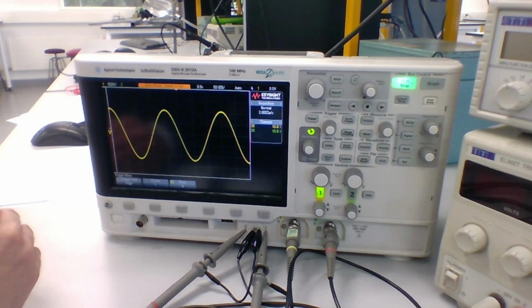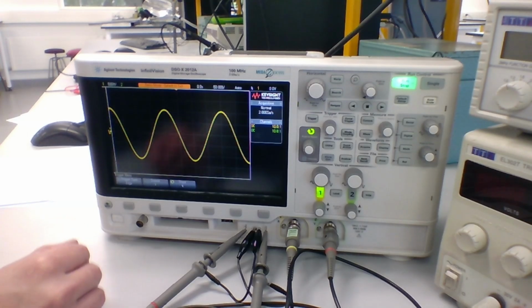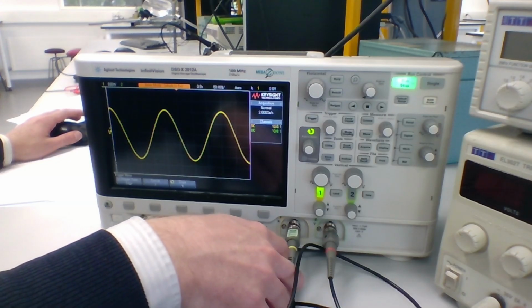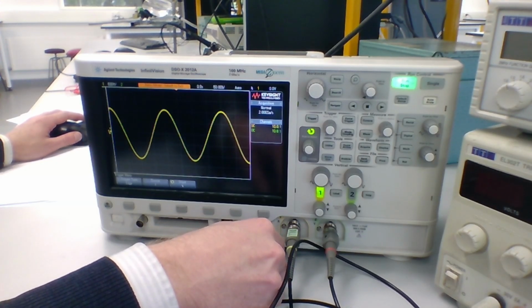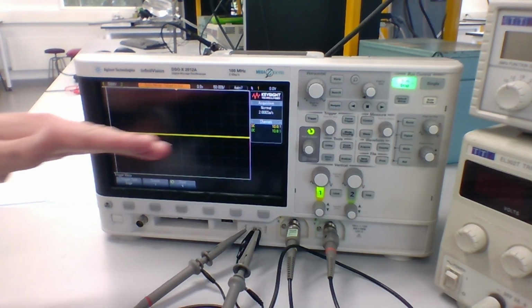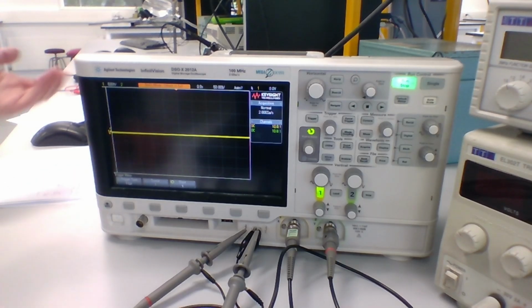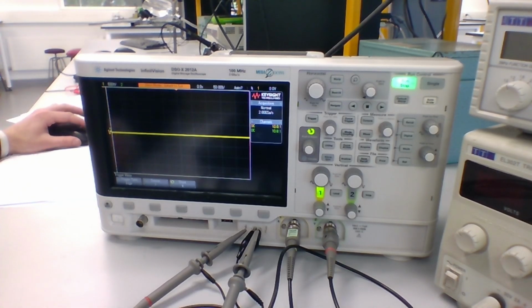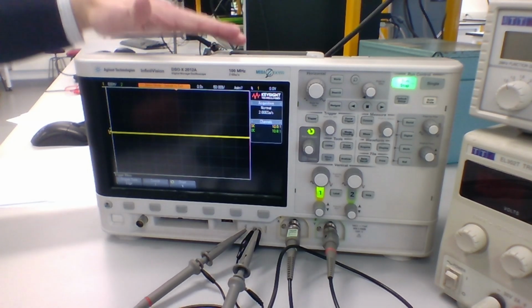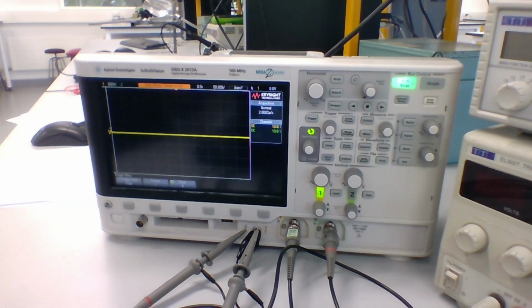Okay. Now what we want to do, following the instructions again, is to disconnect the channel 1 probe from the hook it's connected to. So I'm just going to disconnect that. And we can see our signal goes to a flat line, indicating 0 volts. So there's probably nothing there. What we're now going to do is change our oscilloscope from the auto triggering mode to what's known as normal triggering. So we can do that.